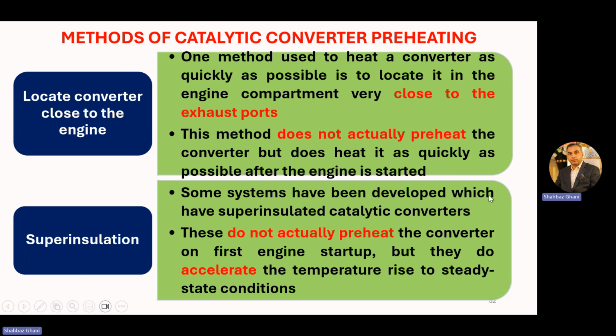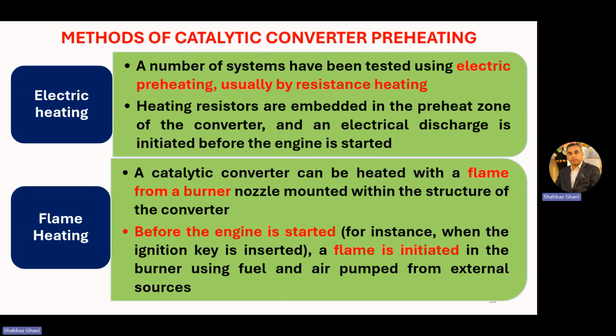Second is super insulation. Some systems have been developed which have a super insulated catalytic converter. They do not actually preheat the converter on the first engine startup, but they do accelerate the temperature rise to steady state condition. So it is also not ideal preheating. In the initial start they do not preheat, but as the engine operates at its normal operating temperature, they maintain that temperature due to super insulation.